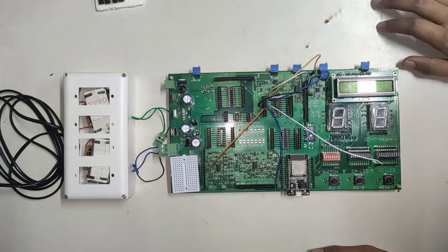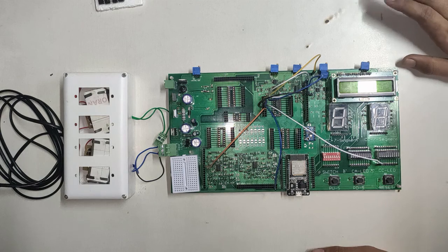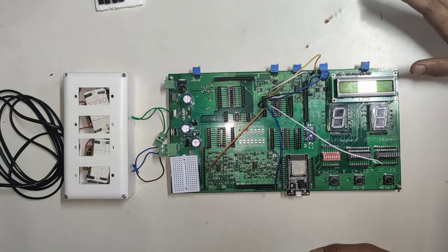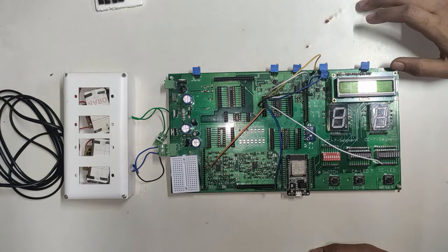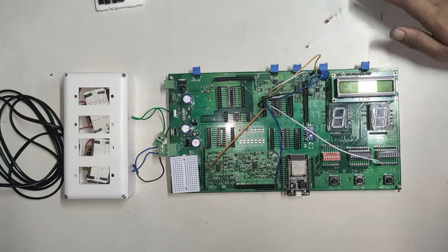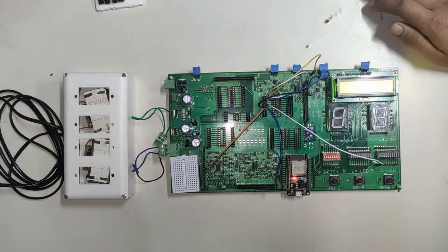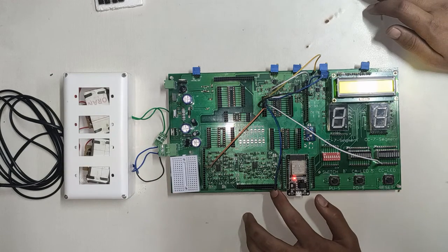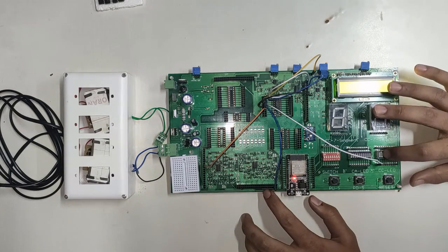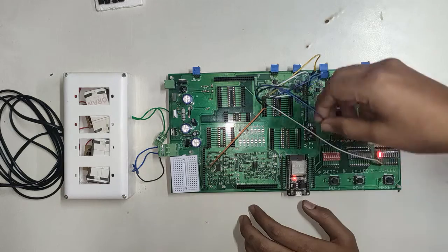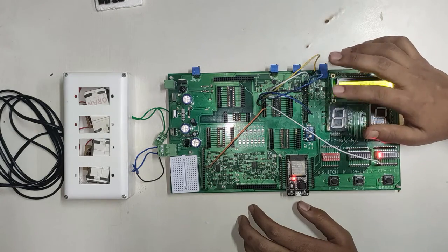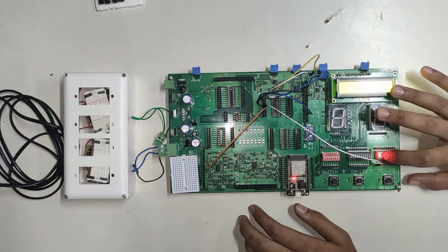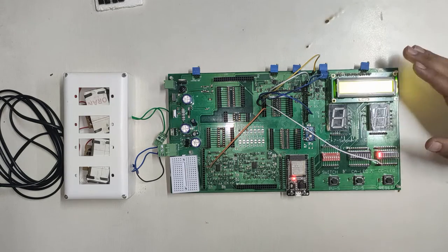So this was the connection, and the output of the D flip-flop is nothing but the input. If we give input as 0, the output must be 0, and if input is 1, then the output must be 1. Let us check it now. Here we can see that the input is ground, which is logic 0, so the output is 0. Now when we give input as plus 5 volt, which is logic 1, the LED starts glowing, which means that the output of the flip-flop is 1.